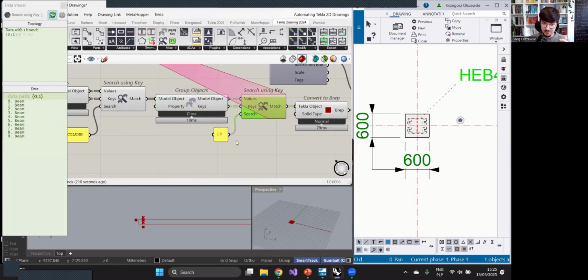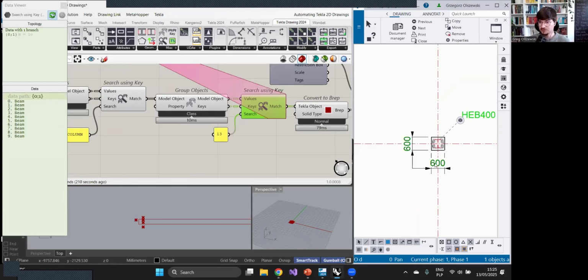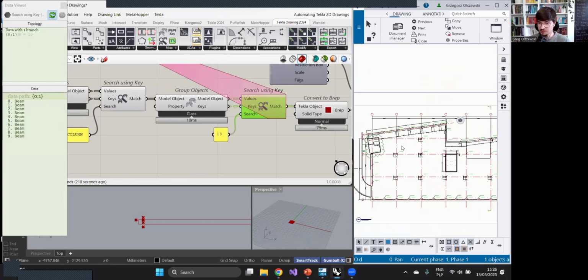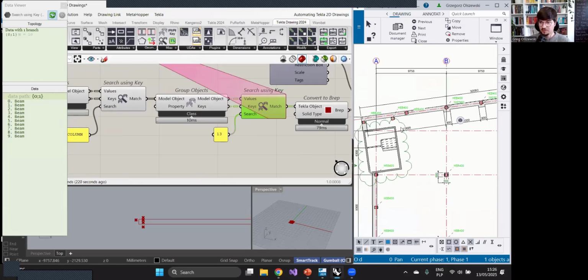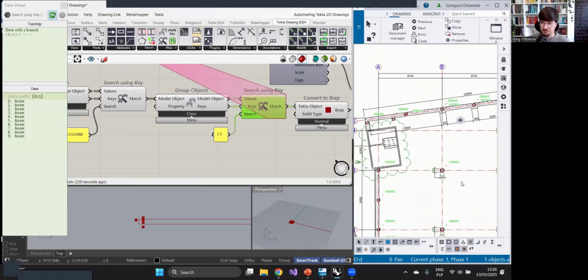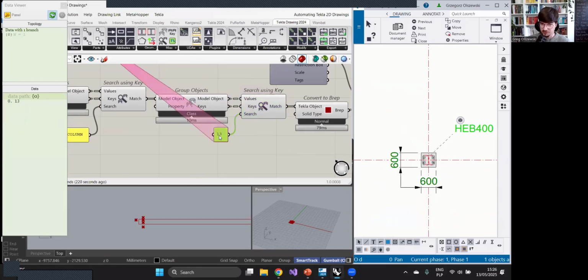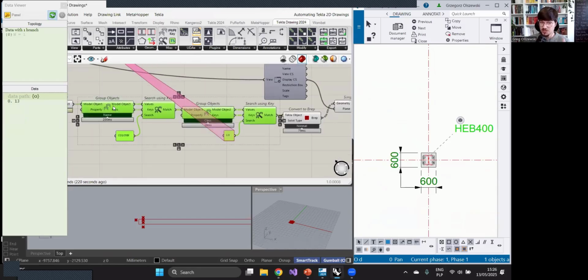And this is the place where I have done the filtering, the pre-processing of the input, because on that drawing, on that view, I see a lot of different elements, some walls, some columns, a lot of things. But I want to dimension a very specific thing, only the column on the class 13. So I have to somehow filter all of those elements according to my needs.